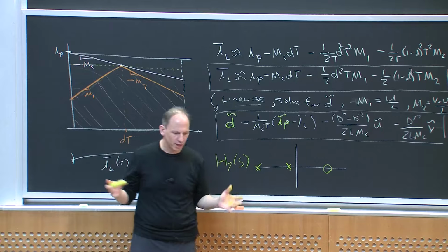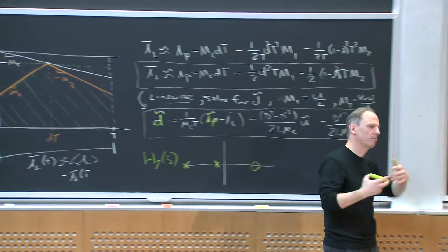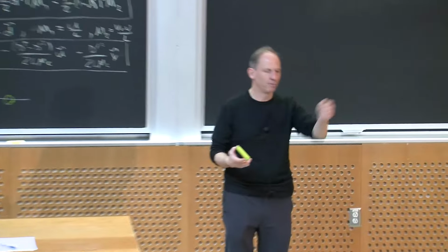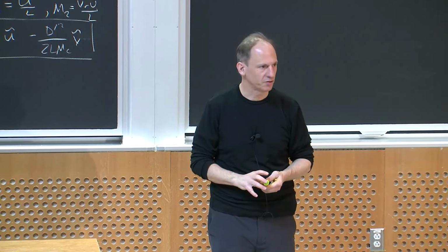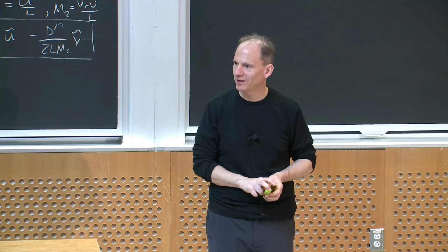So all right, now we can go design Gc(s). I still have a right half plane zero, but it's a much easier plant to compensate, and I can put my dynamics much more nicely than I could before. And I get free current limiting in the process.